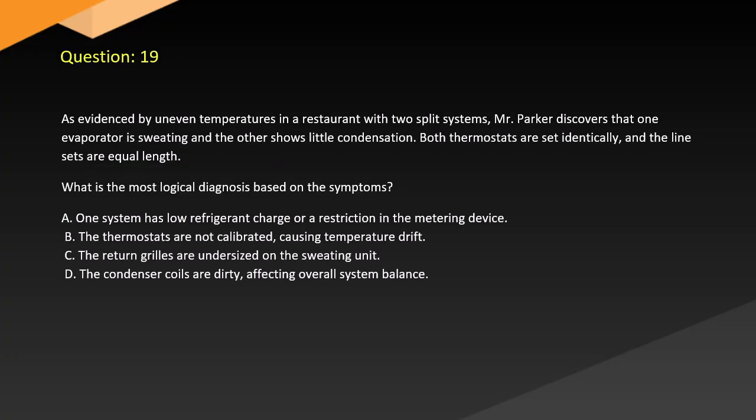Question 19. As evidenced by uneven temperatures in a restaurant with two split systems, Mr. Parker discovers that one evaporator is sweating and the other shows little condensation. Both thermostats are set identically and the line sets are equal length. What is the most logical diagnosis based on the symptoms?